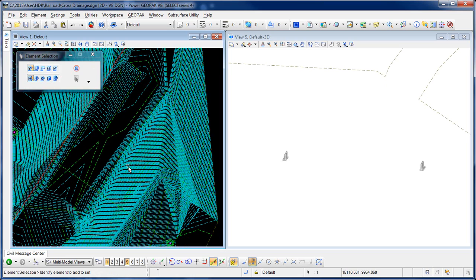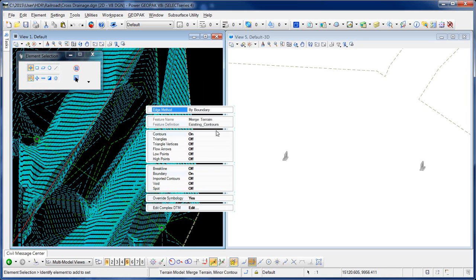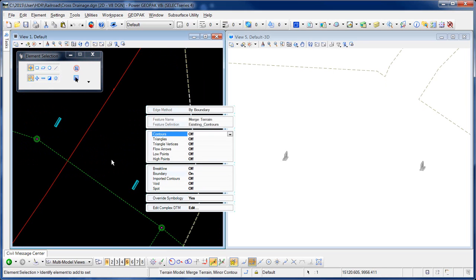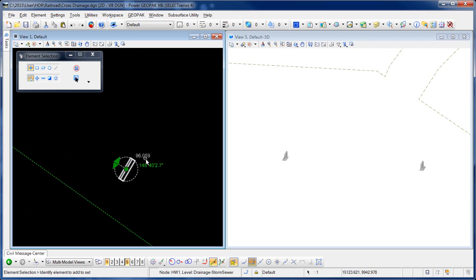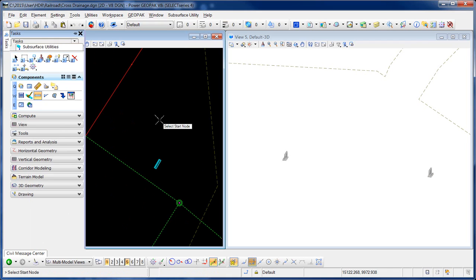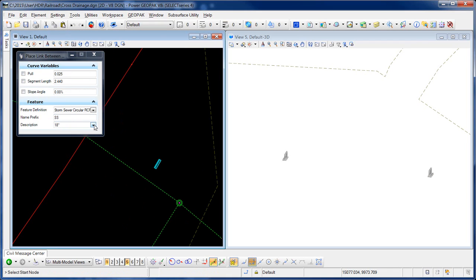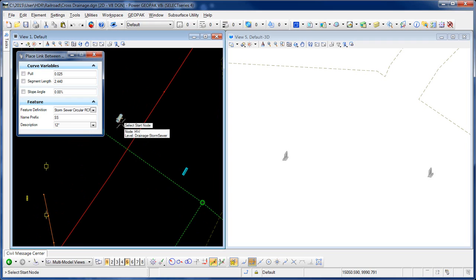And the only reason I had those contours turned on was to help guide me where these slopes were at for the railroad, and so I'll turn those off now. Now let me make a quick check here to make sure 96.12, and make sure I don't have this guy going uphill. 96.05, that's pretty flat. Let's pull it downhill a little bit. So now we've got a little more slope on that pipe. And then I'm just going to put in the smallest pipe that we have, because we're actually going to do a design here.